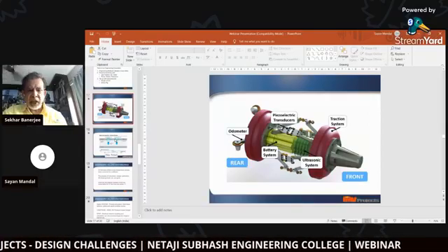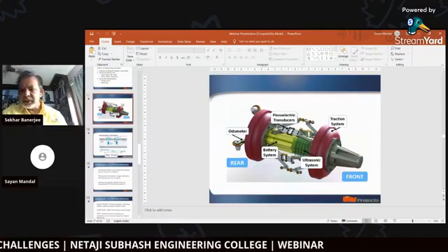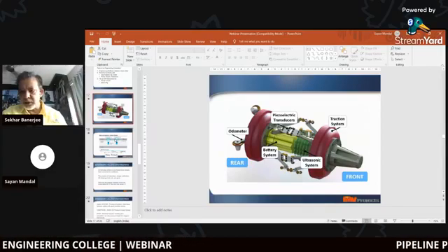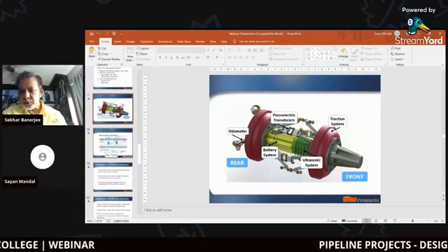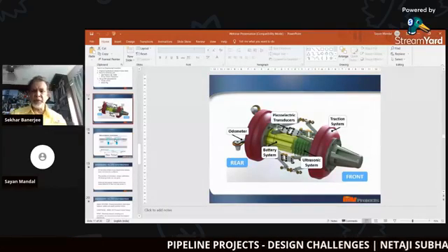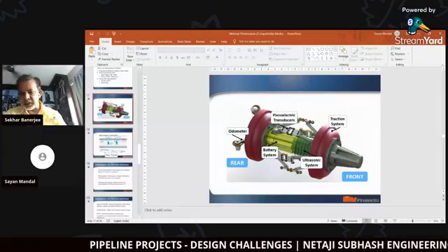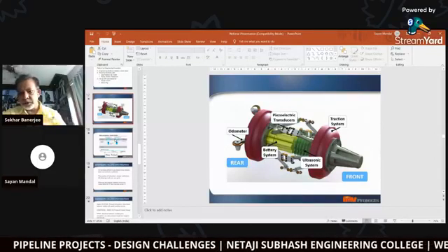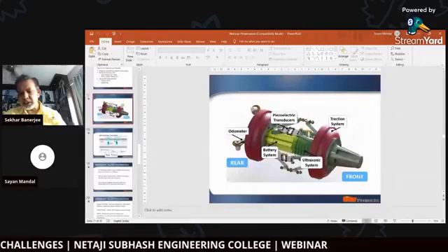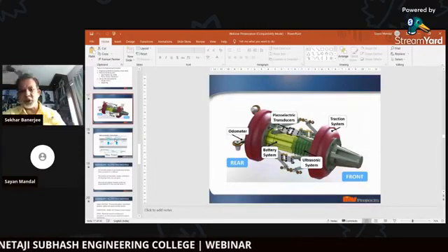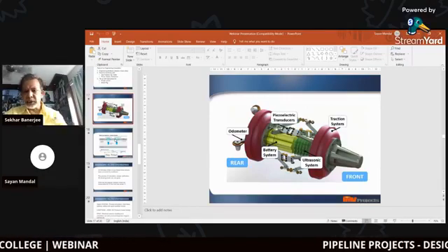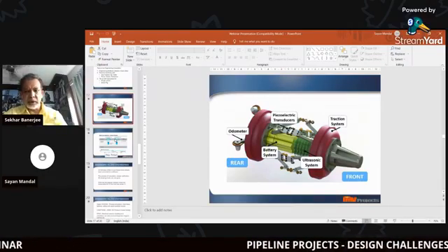They have the ultrasonographic probes on them. Those probes measure the thickness of the pipe throughout its journey, and it records it. When it goes to the end, somebody takes it out, takes the chip out of it, puts it into a computer, and we get a very clear picture of the thickness, or the health, of the pipeline.